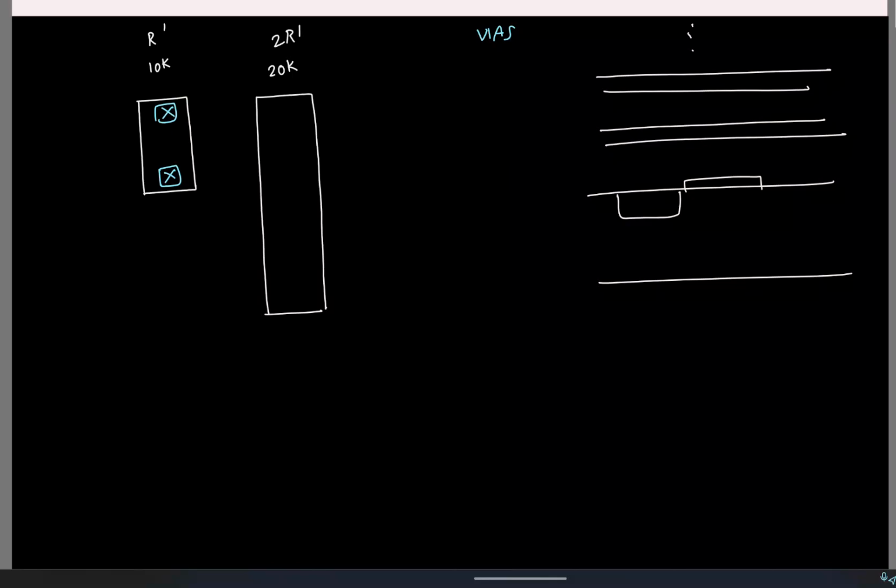So basically, we'll be putting some contacts or vias like this, say from diffusion to poly. Metal contacts. Basically, it is something that connects the two layers. That's all. Even between metals, you will have vias so that you can connect one metal layer to the other. Okay. So same will happen here also. We'll have them. Now, if you see the metal will be connected like this.